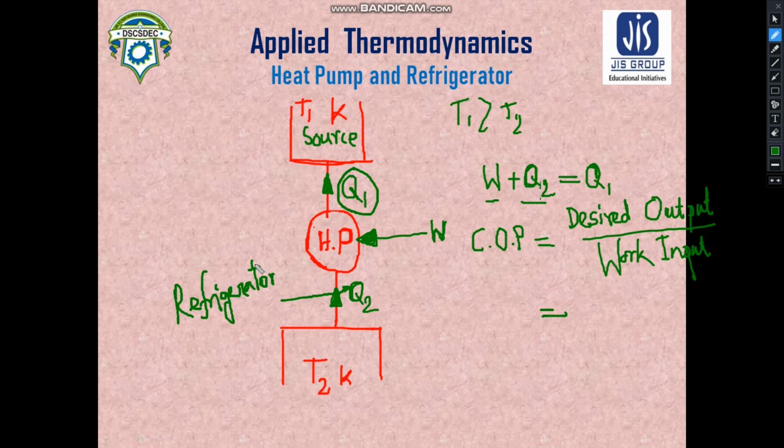Okay, that means you need to keep your room warm, your surroundings is at a lower temperature. So what will happen? Heat will flow from your room to the surroundings. So heat is going to flow from your room at a certain fixed rate to the surroundings. Now you will provide some external heat input to your room so that it balances the heat which is going outwards. Okay, so here comes the importance of a heat pump. With the help of a heat pump, you can transfer heat into your room so that it balances exactly the heat which is going out to the surroundings.